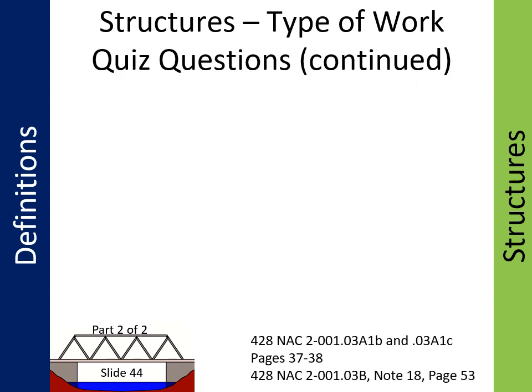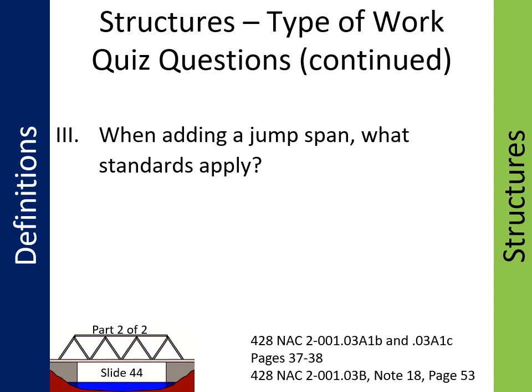Question 3. When adding a jump span, what standards apply? The answer is new and reconstructed standards apply to a jump span. To review, a jump span is an extension at the end of an existing structure necessitated usually by a flood event or events which severely scour an erodible embankment.